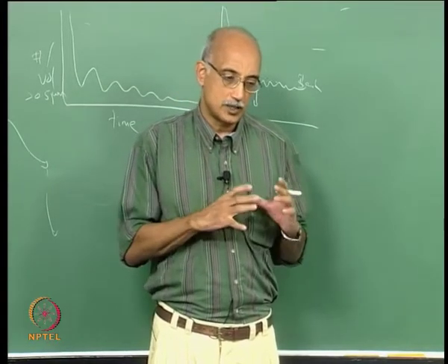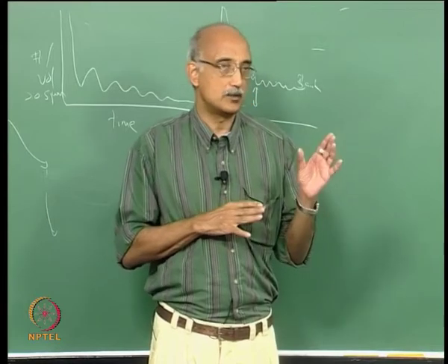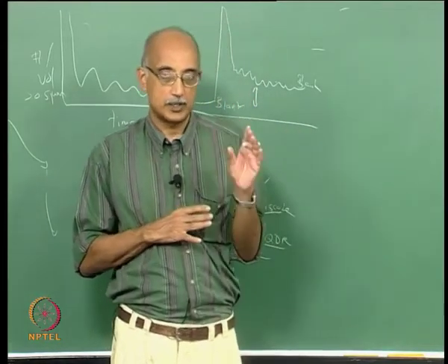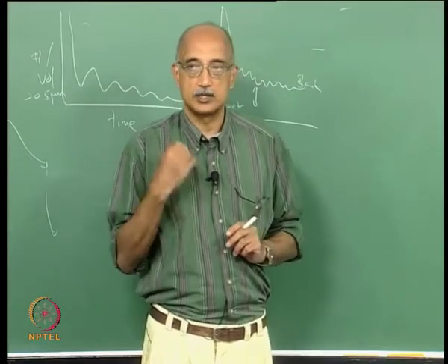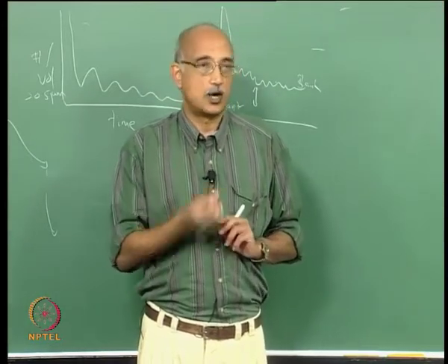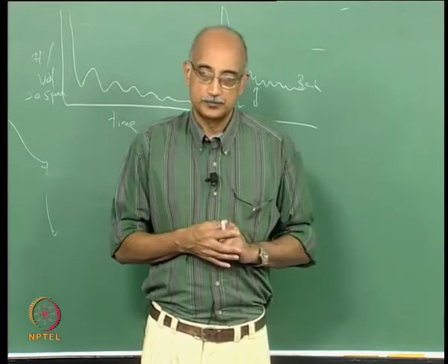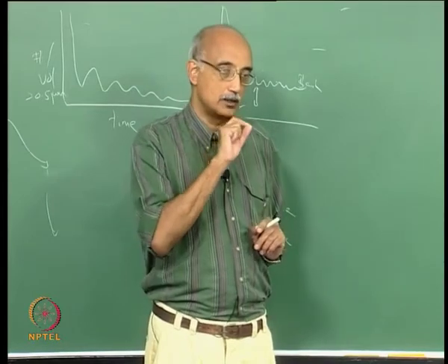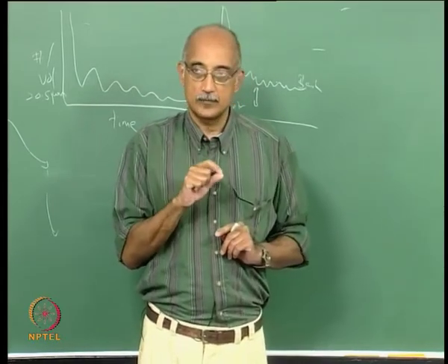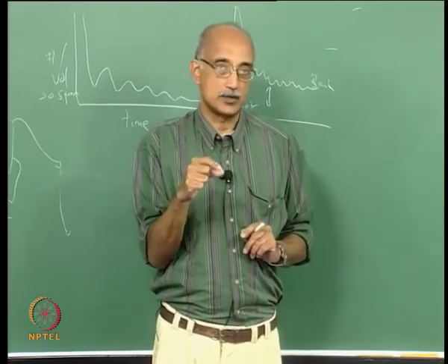So, whether it is a thermal process for getting the vapor, or a sputtering process where the surface is bombarded with ions or plasma to form the vapor, the key is to maintain the homogeneous kinetics in such a way that particles do not form in the gas phase.